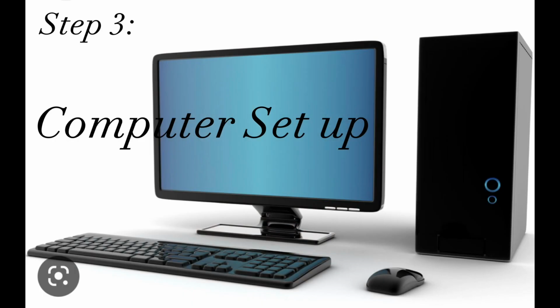Step 3. Computer setup. When setting up the computer, what must you do? Well, firstly, open the software. By doing this, you'll see a spanner-like icon located on the top left-hand corner of your screen. Clicking this will open up the setting window. In the setting window, you'll see a drop-down menu under Materials. Now click this and select your code name. Since your specimen is steel, you'll select S235 JRC plus C.